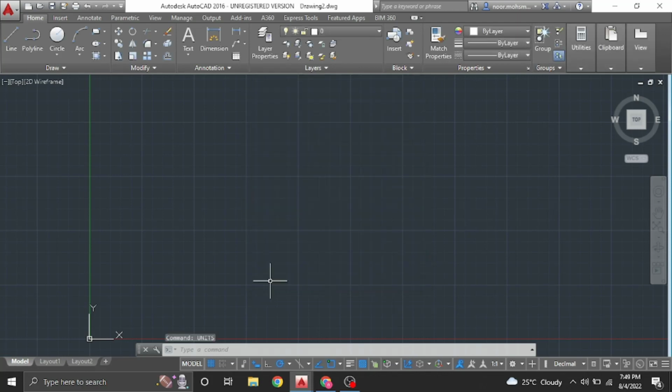So for the software, we have given the instruction that whatever drawing I am going to draw is in terms of millimeters. Okay, so the insertion scale is millimeters. Then the type of length we have used is decimal, and the angle also is decimal. And now, after giving the insertion scale, first we need to define the drawing area.